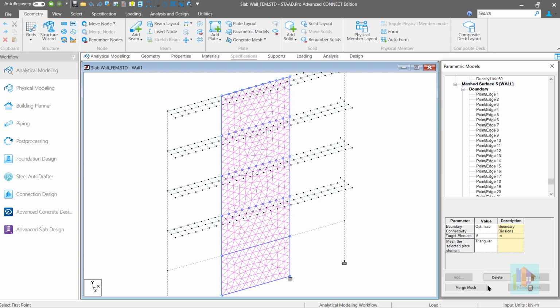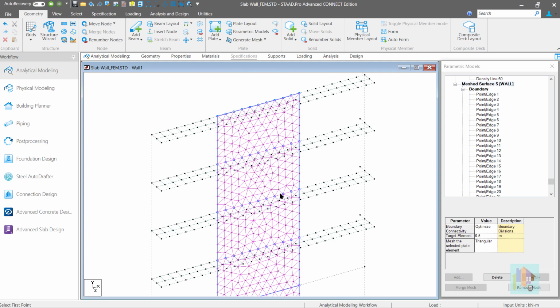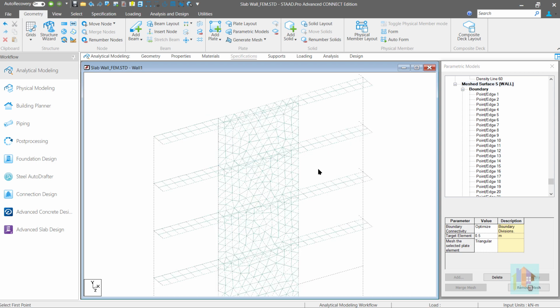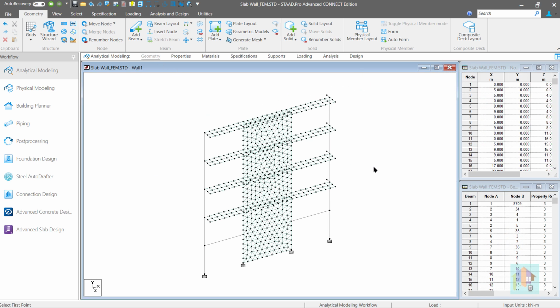See, all existing nodes of floor panels and members are considered during mesh generation. We don't have to count or provide the boundary division to maintain the connectivity. It's not only for a single layer, but all existing floor panels are considered during wall generation. If we want to generate a mesh connecting multi-level surfaces or members, parametric model is the best option.